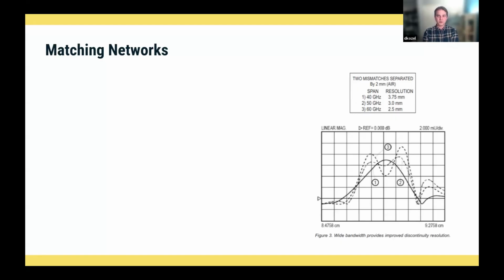Once you're getting below -20, -30 dB of return loss, calibration, which most things can get, is just enough to measure. If your attenuator is working to that degree, you can measure a 30 dB attenuator. If your bandpass filter is rejecting at least 30 dB, that's probably enough for a lot of applications. And as we can see, a NanoVNA easily exceeds 30 dB of range.